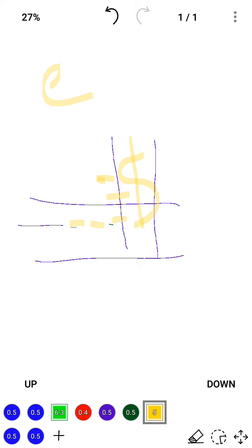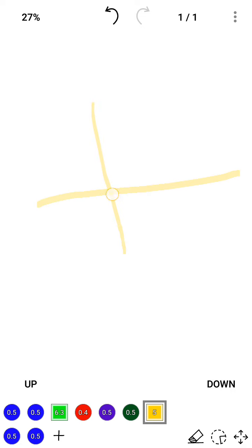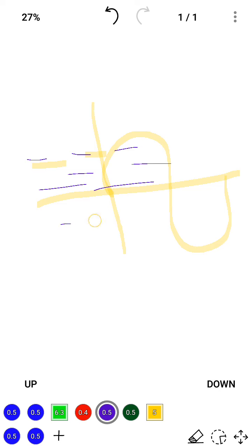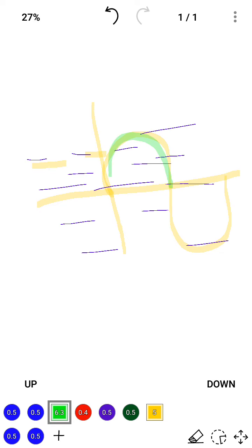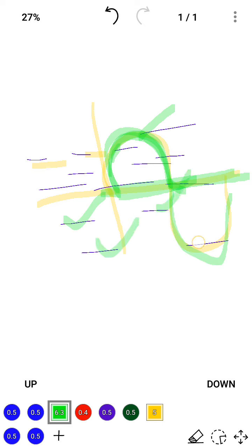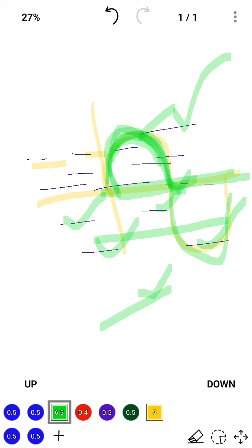The resonant signal is like this, and electrons are coming from the electron gun. The electrons traveling in the positive cycle have their velocity increased, because they gain energy from the positive signal. Electrons traveling at the zero crossing have unchanged velocity. Electrons traveling in the negative cycle have their velocity reduced, so those are called decelerated electrons.